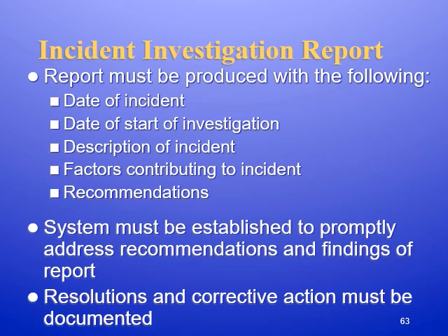An incident investigation report must be produced with the following: date of the incident, date of the start of the investigation, description of incident, factors contributing to the incident, recommendations. A system must be established to promptly address recommendations and findings of the report. And resolutions and corrective actions must be documented.